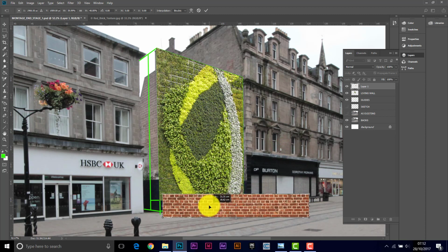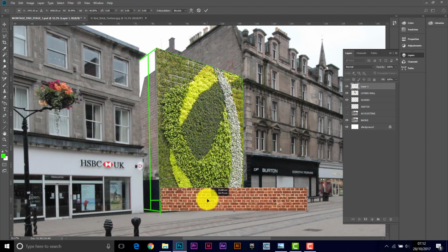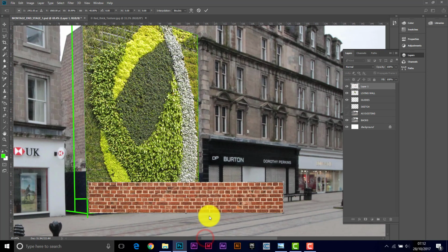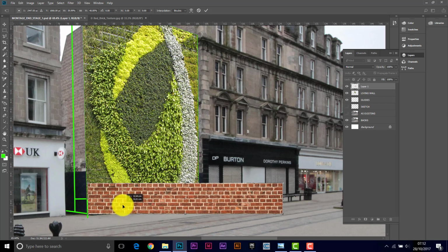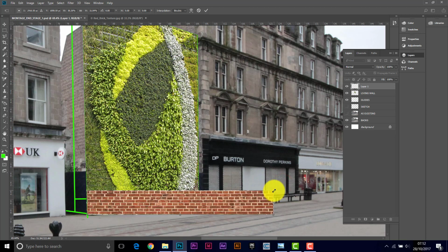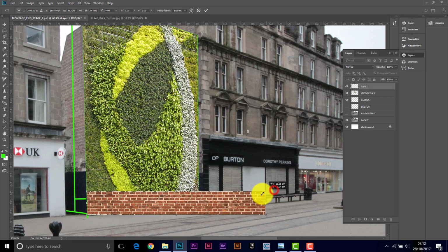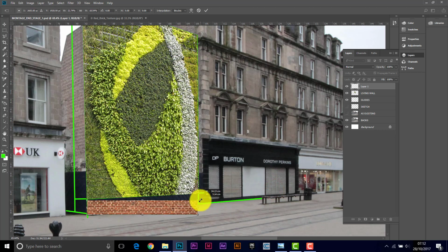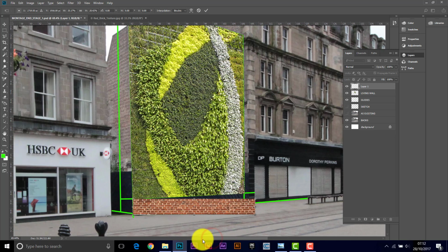Okay, and if I place it carefully in the corner there, and then do my scaling, sorry, wrong button, hold Shift, and drag the corner, I can match the height at that near edge. Could have done it at this end as well, either way would be the same operation. So that's scale wise, that's looking pretty good.